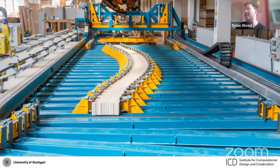So the basis of any type of glue laminated curved structure, like what I showed in the previous slide, is that you need some type of existing shape to push against the wood in order to change it from this rather linear shape and elastically bend it into a curved shape, and then hold it while it's being glued. The problem with this is not that it's necessarily impossible, but it makes it significantly more difficult and also more expensive to produce curved geometries.